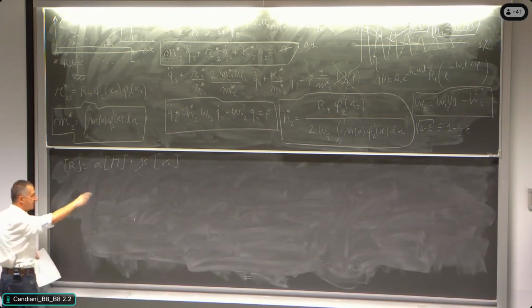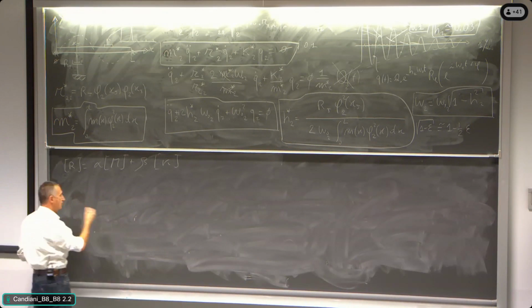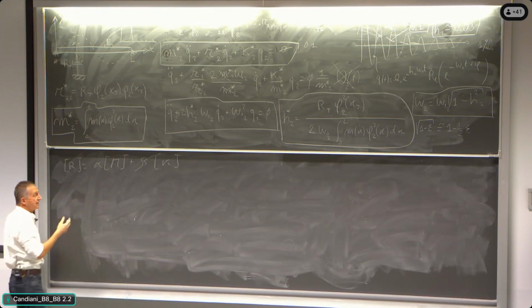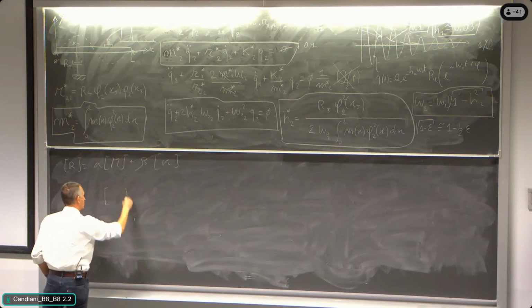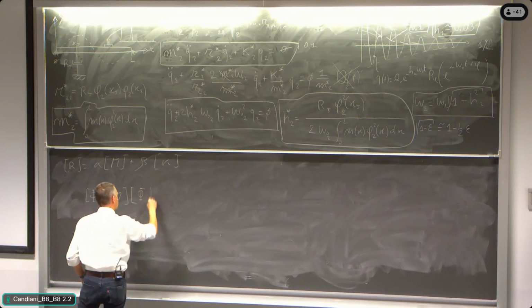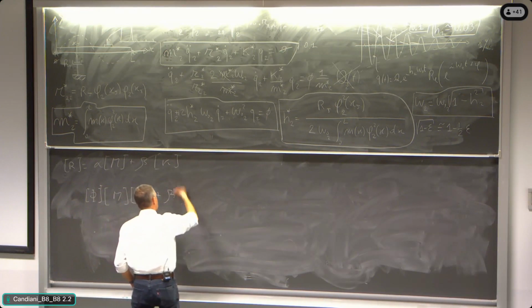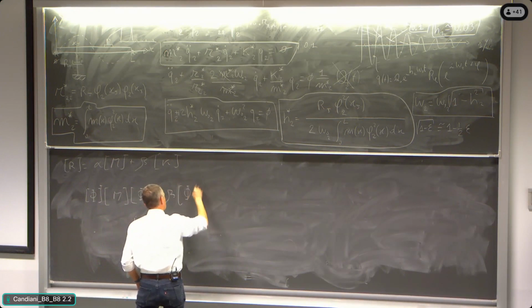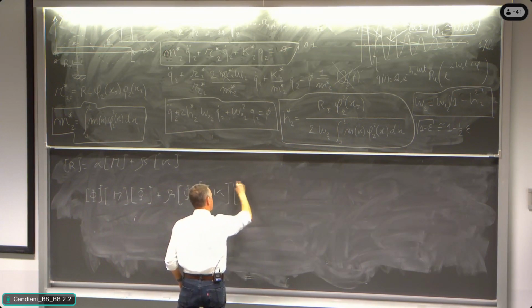But then the real point of this representation is that if we are moving into the principal coordinates, and making the transformation of coordinates, the transformation is made by multiplying the mass matrix times phi transpose and phi, the matrix of the eigenvectors, and so plus beta, and here we repeat phi transposed stiffness matrix phi.